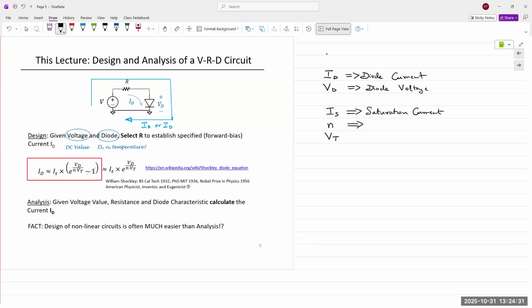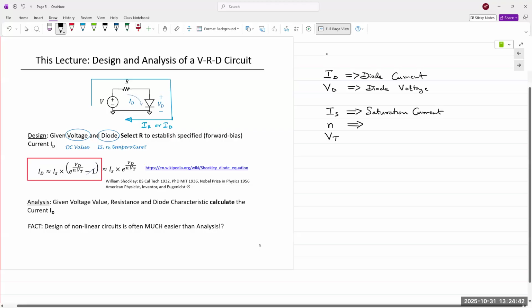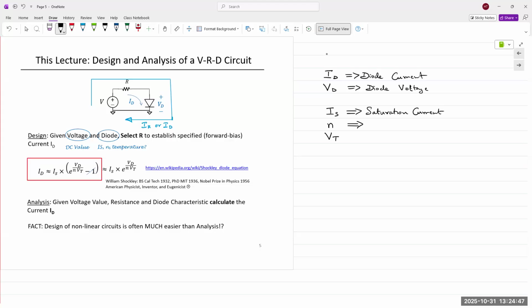So when we apply a voltage on opposite sides of the PN junction, there is a small current that results because of the flow of minority charge carriers. That is known as the saturation current. The reason it's so small is because the number of electrons and the number of holes is very, very small compared to the other majority charge carriers. But again, that's about as brief as I can get with describing that. That is a topic for spring when you will take 315.